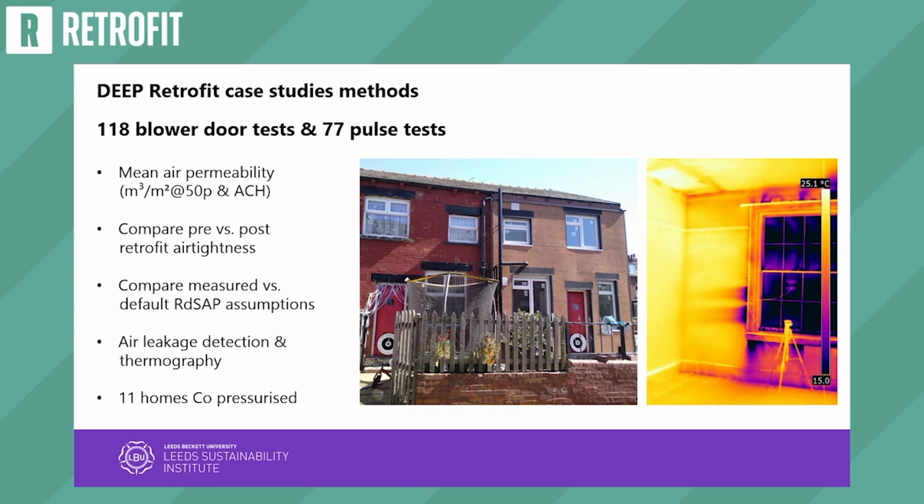So unless you're pressurizing the neighboring property to exactly the same pressure as the test building, you may be over-reporting your internal to external heat losses. People who understand that sentence know how important that is, but most people won't really care.